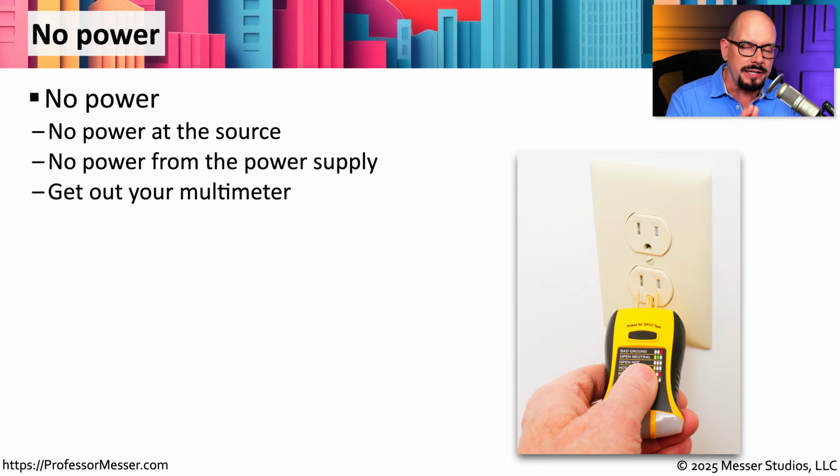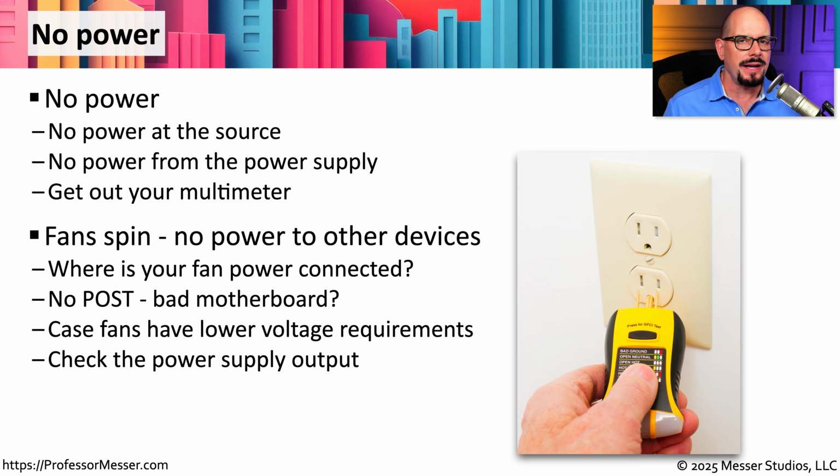You'll need to check a number of different components to see where the power is and where the power might not be. One of the best ways to do this is with a multimeter to be able to check not just the AC power that's in the outlet, but the DC power that's coming from the other side of your computer's power supply. You might also find that some components within the computer are working properly, but other components aren't working at all.